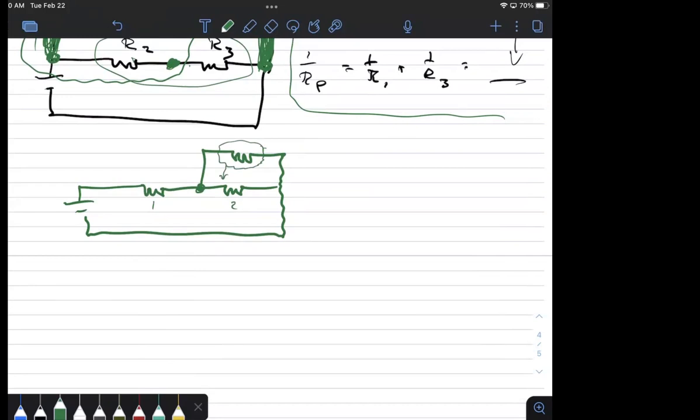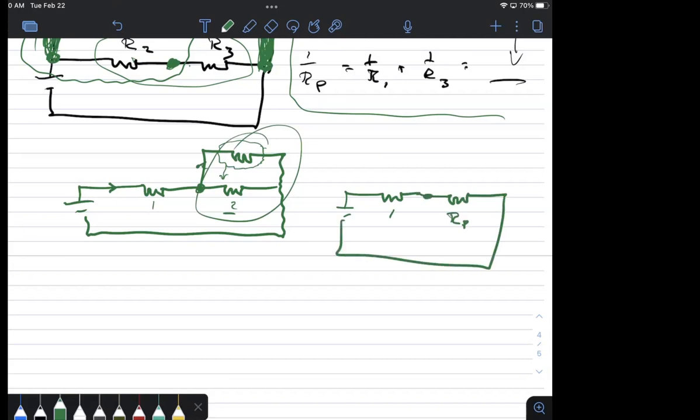He's connected to them. So in other words, an electron that comes in and hits the first resistor will not necessarily hit the second resistor, because the electron may go up this way instead. So I can't do the series yet, but I can do the parallel first. Work the parallel first, you get some equivalent resistance, and then when you redraw it, this guy's still R1, and now this thing is whatever the parallel was. And now you can see this is definitely series.